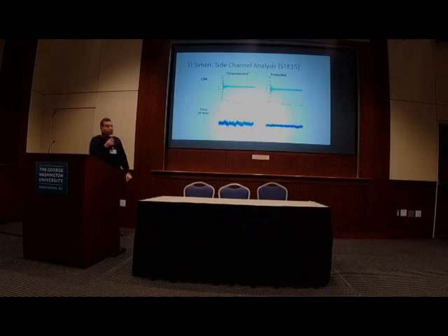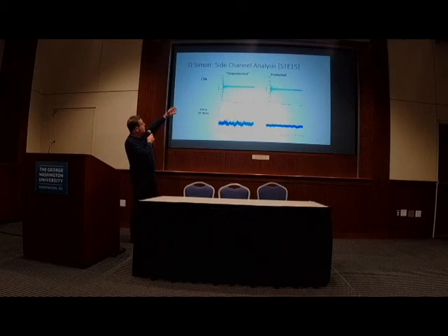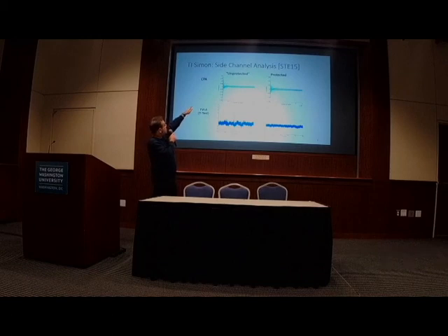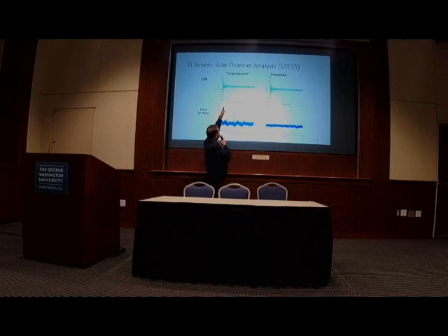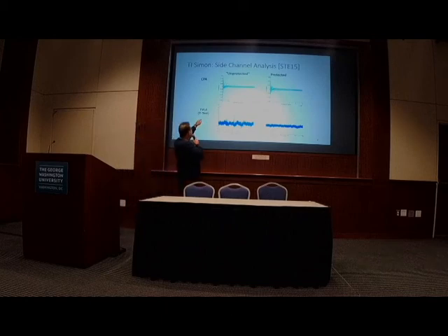You see an unprotected Simon implementation on the left, and all of these are different key hypotheses, each trace here. The red one is the real key. It starts sticking out with even just a small number of traces, a few hundred traces. This is the Simon implementation, right? And test vector leakage assessment is a way of actually assessing.